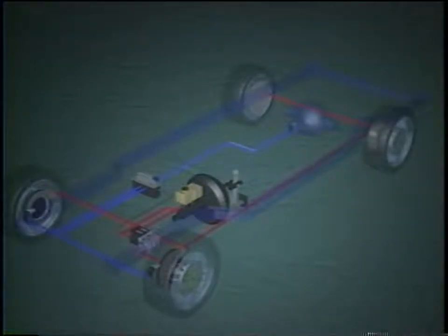onboard computer. In a braking situation, if the computer determines that a wheel is about to lock up, it sends a signal to the hydraulic modulator to automatically adjust brake pressure several times a second as required. This allows the driver to retain steering control while providing a higher braking force on most surfaces than a locked wheel provides. ABS is an added feature to a brake system. In the event that the ABS feature is disabled, the vehicle will continue to have use of its conventional brake